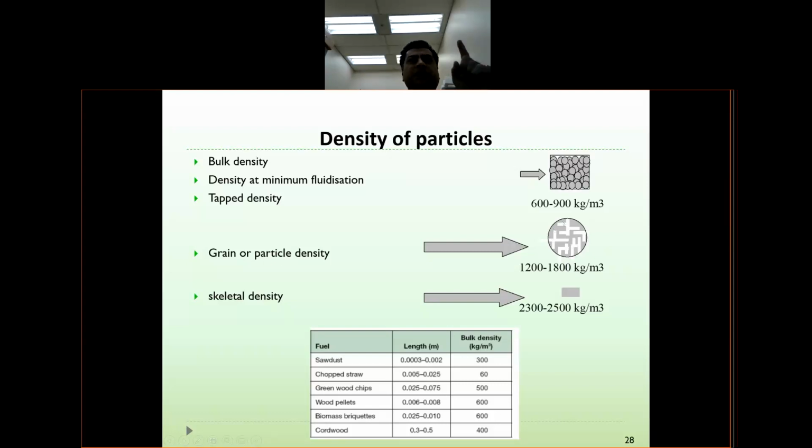But specifically about biomass grinding, the efficiency of biomass grinding, or in particular the energy consumption in grinding of biomass, depends on some factors such as the type of the biomass, humidity of the biomass, granulometry of biomass, in other words shape of the biomass, density of the biomass, and the type of grinding equipment that you use, also the flow rate of feeding.